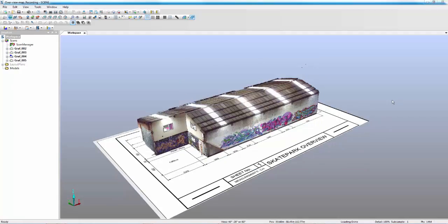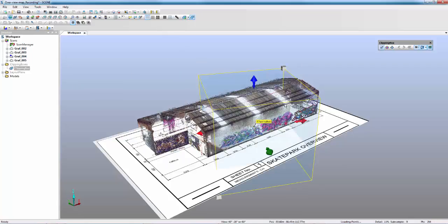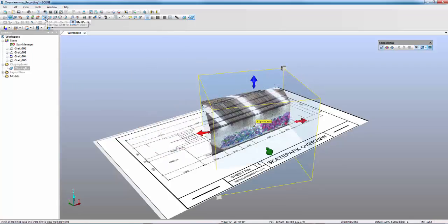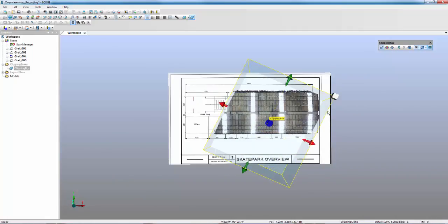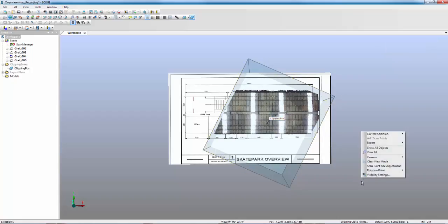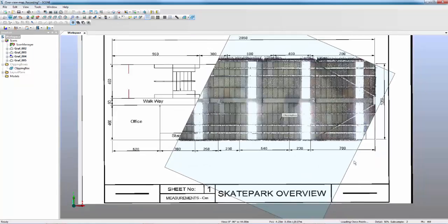Now, after a slight pause in the recording to allow the project point cloud to be created, I've now got my scans unloaded and my project point cloud active on the screen, which then allows me to go in and create a clipping plane. Using similar tools to how we created the other image, firstly I'm just going to modify these and on the screen check that I'm still in an orthographic view, which I wasn't, so I'm just going to modify that back.